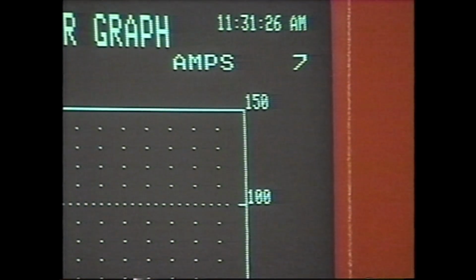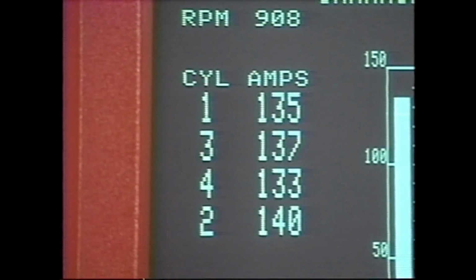Charging system problems will show up after the engine starts and the cranking amps test is complete as a low amps value. This is a live reading from the alternator. Note the lowest and highest cylinder amperage values. Greater difference between the values indicates greater differences in cylinder compression.